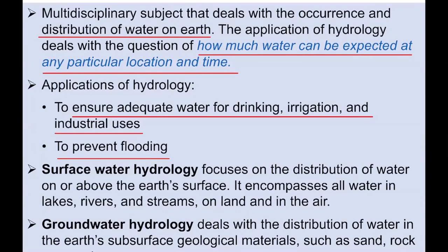So for example, when we try to urbanize an area, we have to consider what the drainage is for the water. Let's say if there is severe precipitation, severe rainfall, we don't want to create a flood within the city, right? So we don't want to change the soil structure a lot. And we actually want to evaluate the soil properties to see how easily the water can flow through them, right? If they're too dense, then most of the water will just get stored in the city, instead of getting drained.